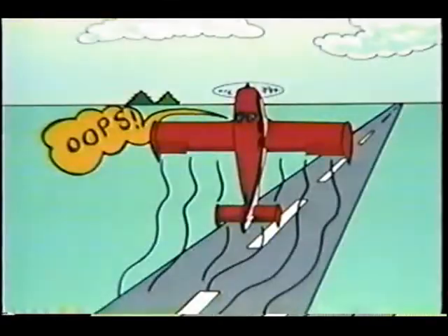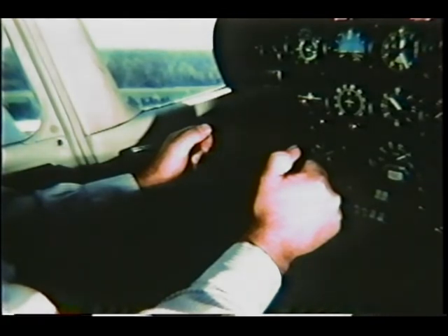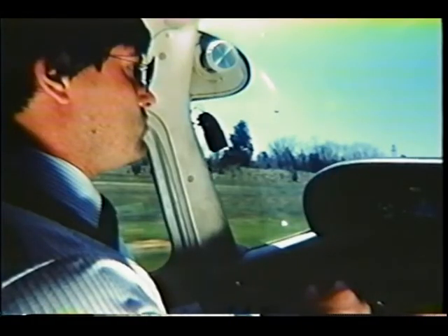And make sure you trim the airplane to maintain proper pitch control, or else... This is what we call the prelude to a hammerhead stall. So remember, until you've adjusted your trim, be prepared to apply some pretty heavy forward pressure on the controls to maintain the proper pitch attitude for climb. And use your attitude indicator to help you establish and maintain a positive climb. But if you're VFR, don't fixate on the gauges. Use outside references.